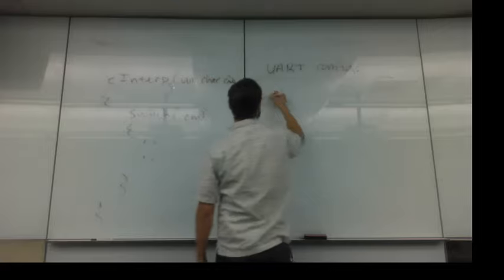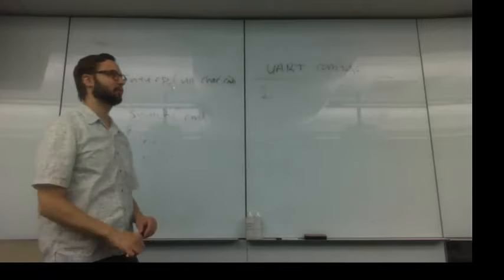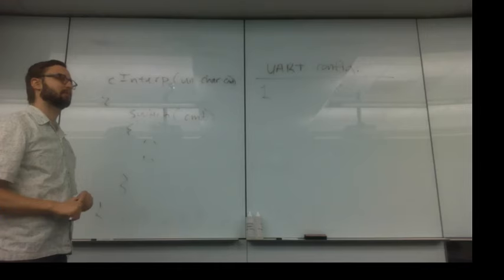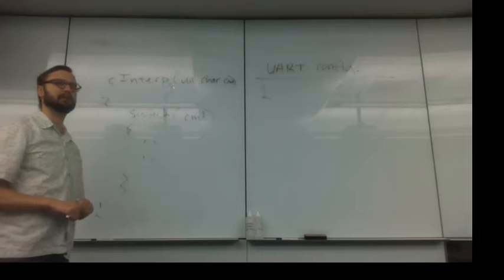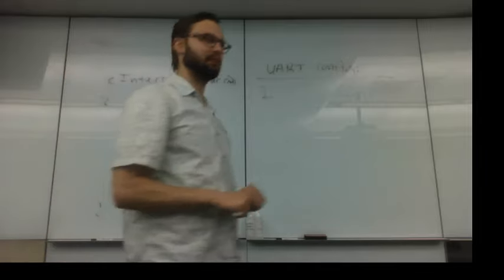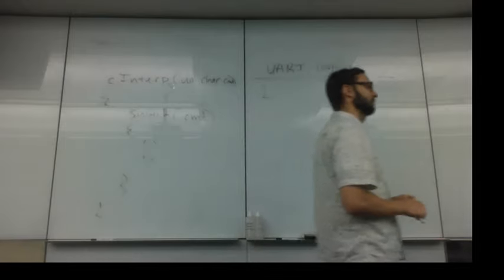What's step one? Anybody want to take a crack at what step one would be? Write appropriate values for data, parity and stop bits. So that would be in the UART mode register. I guess you could do that first. I was thinking first, what about the input and output pins? The tri-state register, right?